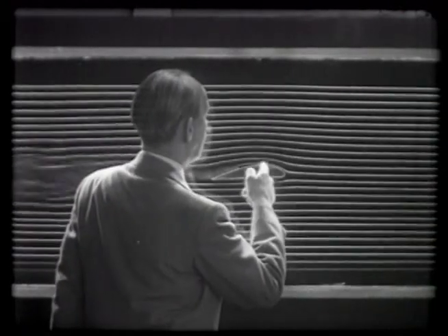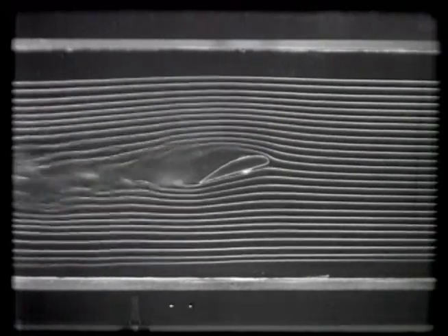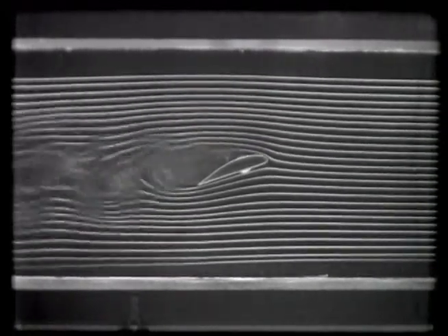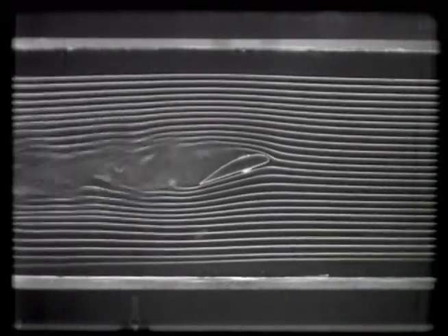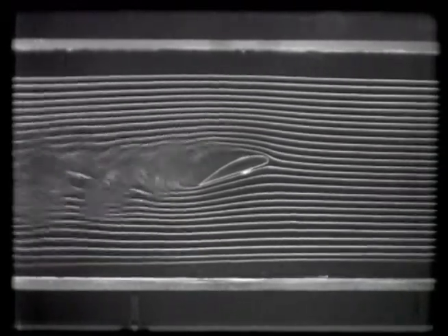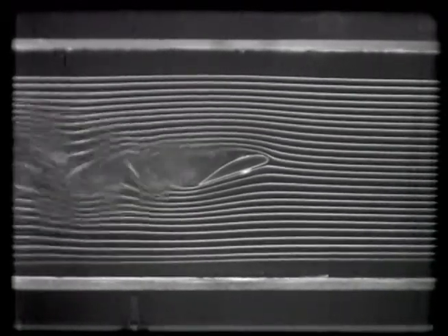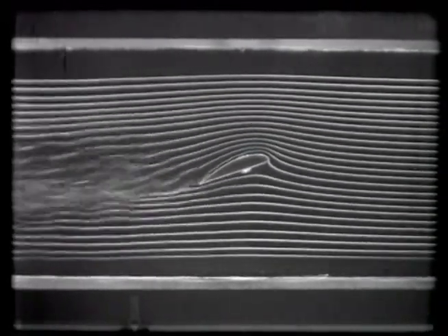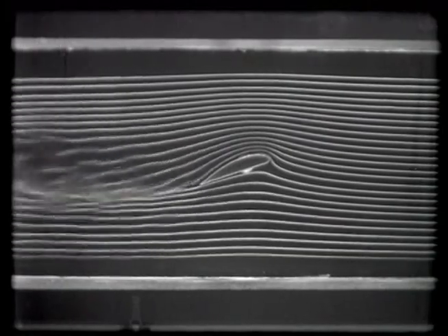Here one in front, the next. These are 5 different slots, and you will see that when we now first give it a large angle of attack so that it stalls, and we put suction on it, then it reattaches, and we can go to very high angles of attack to prevent the stall, as you see it here.